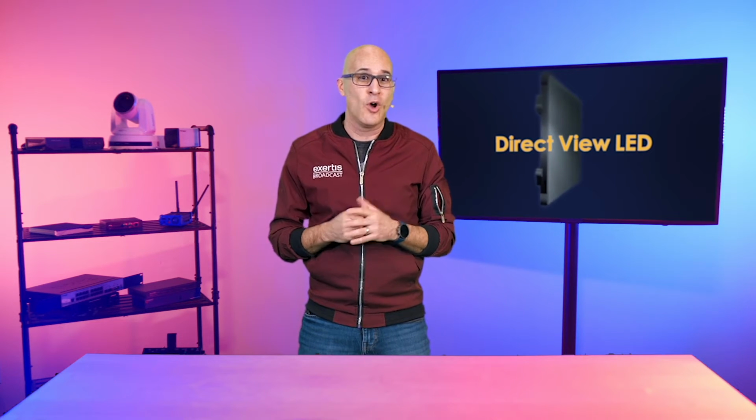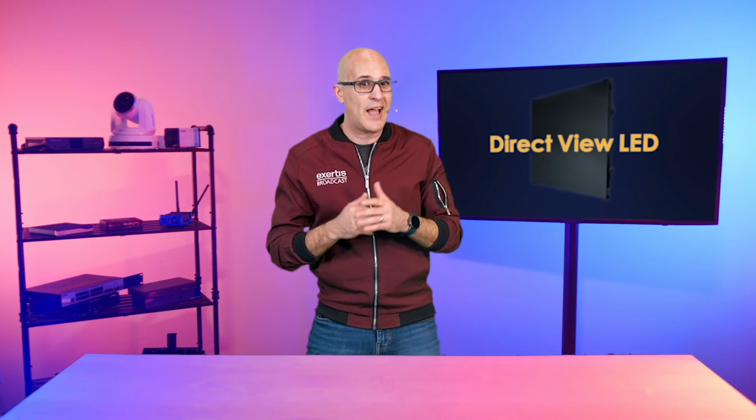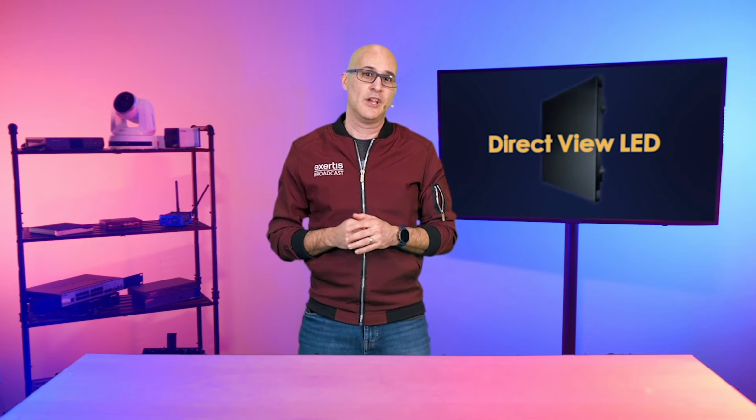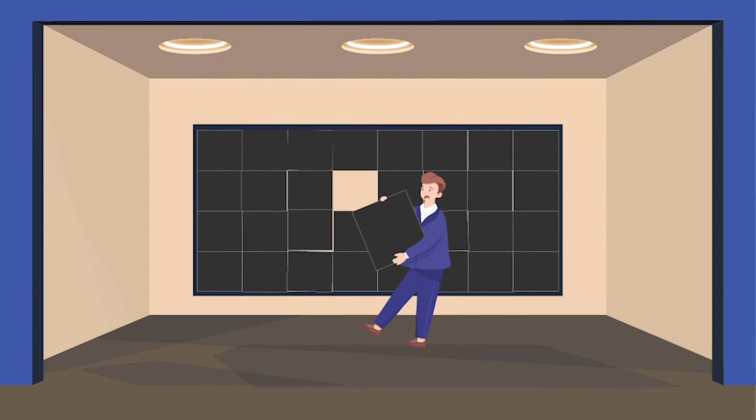The surface you choose must be completely flat and level, or the individual pixels of the wall will drift and bend, creating what's called the Christmas tree effect, where jagged edges affect the integrity of your image's lines. Trust me when I say, it's not the tree you want to put up for the holidays. The structure may cost more than you expect, but a bad mounting structure can make even the most expensive LED wall look bad. Don't skimp on this aspect of your install. This is where I'd always advise you to seek professional help and try not to install it yourself.